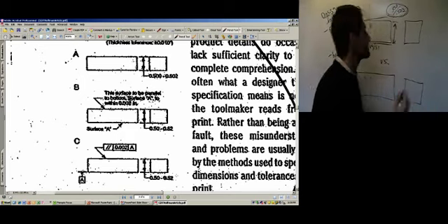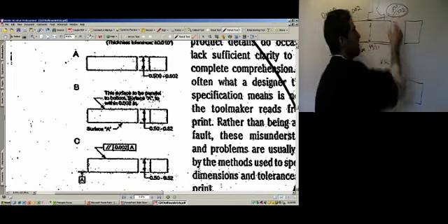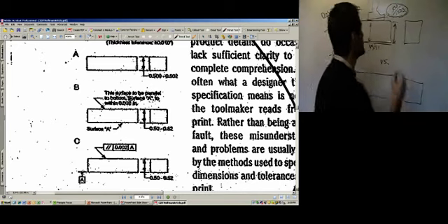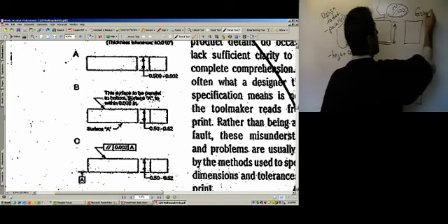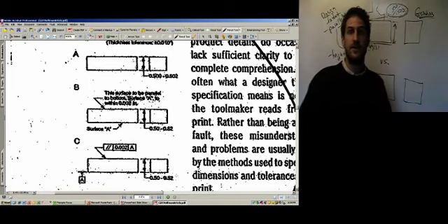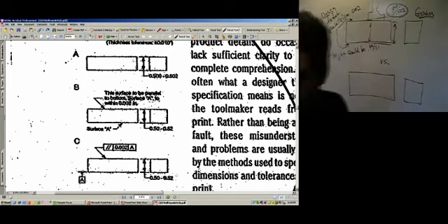You have to go down and touch off the face mill and set the height and everything. So getting it within plus or minus a thousandth, that's going to be pretty tough. I'm going to have to grind it. So this is going to mean grinding. Grinding is expensive. I don't want to have to grind. It takes too long.